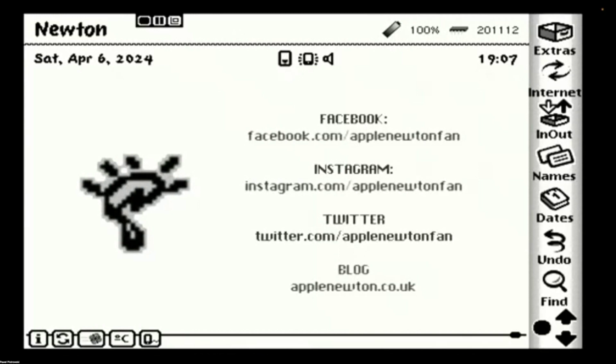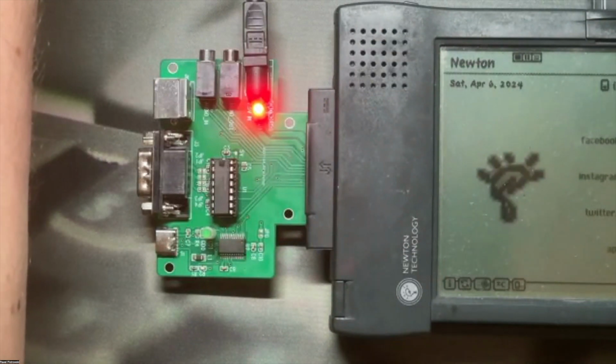But it's so cool, because I do not even need this board most of the time, because I'm doing all this with a program that I've written myself, and Einstein. I have written a program that can change and create a new ROM, and this takes only seconds. And once Matthias had taught me how to locate the strings in the ROM, they are preceded by a certain amount of bytes in a certain order, and they are followed by a certain amount of bytes.